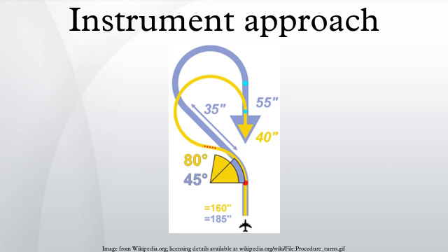Reverse sensing does not occur on a horizontal situation indicator, which gives correct course guidance during both front course and back course approaches. The unshielded localizer transmits in both directions to give course guidance. Because the glide slope is not transmitted on the backside of the localizer, a back course approach is classified as a non-precision approach as it has no vertical guidance. The glide slope indications during a back course approach must always be ignored.